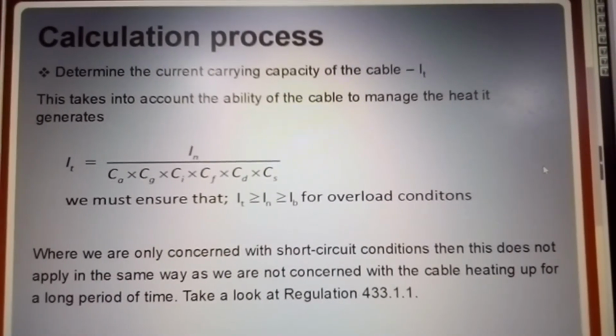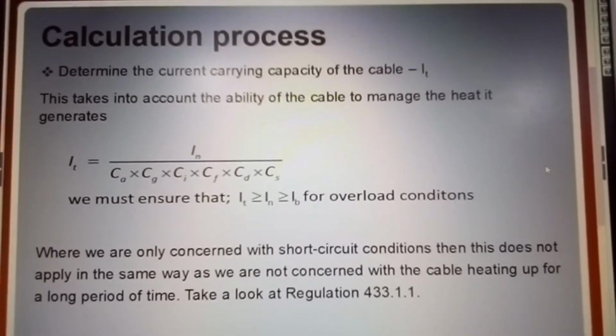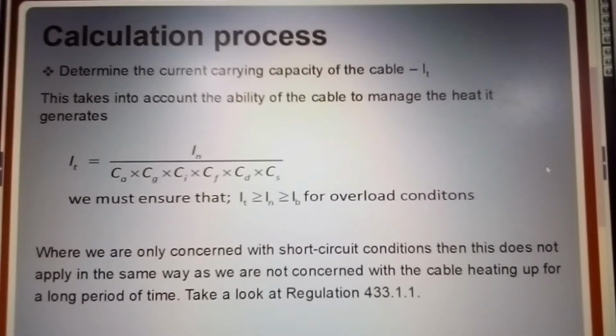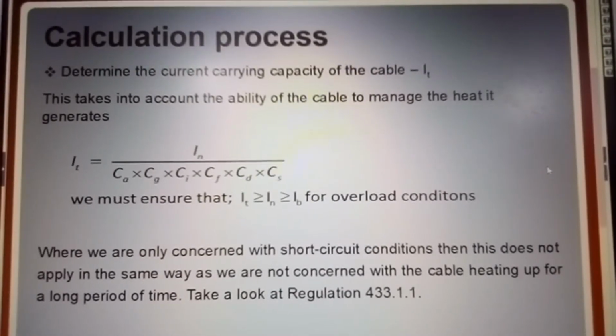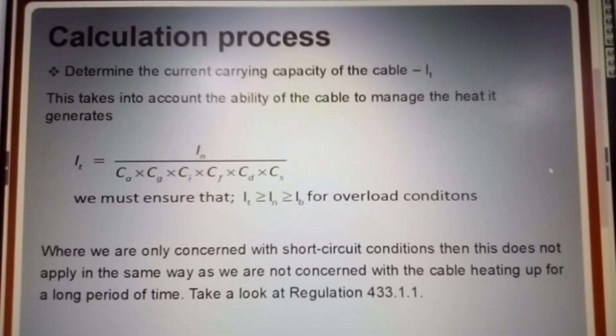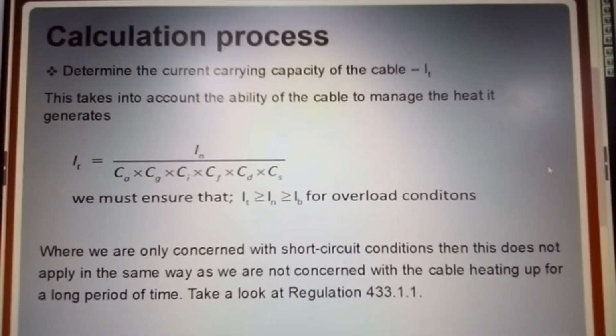Where we are only concerned with short circuit conditions, then this does not apply in the same way, as we are not concerned with the cable heating up for a long period of time. Take a look at regulations 433.1.1. Make sure that you're looking at the correct regulations in regards to the new 18th edition or any future editions that may come out. Okay.